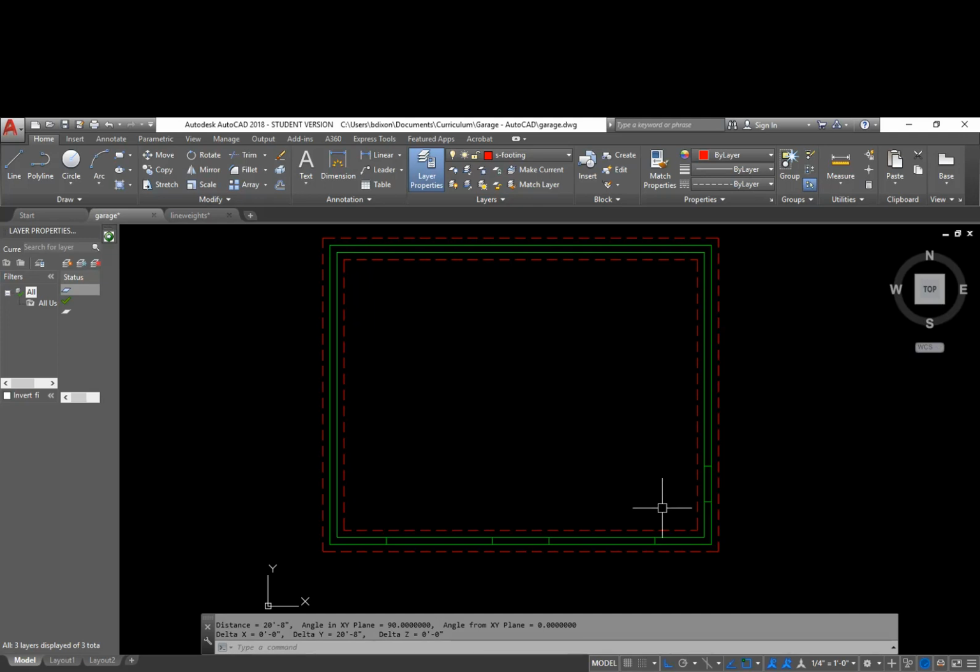So in this direction, this was about 28 feet. And in this direction, it was 36 feet. So I can real quickly and easily look at this and see that I'm going to need a cut joint there, and I would probably need a cut joint here at 20 feet.